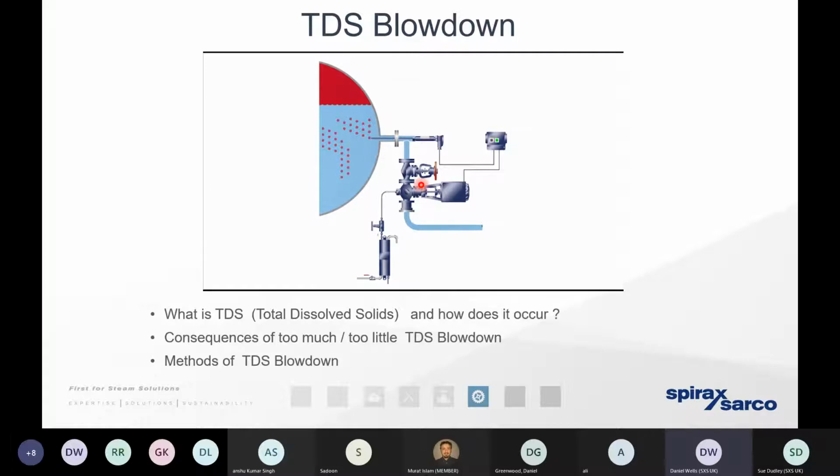The TDS needs to be at an appropriate level, and we measure it in parts per million. So typically the TDS could be managed by taking a sample from the side of the boiler on a daily basis, putting conductivity probes across that cooled sample. High conductivity, it's an indication of a high concentration. We open a valve at the side of the boiler. We bleed out a couple of gallons of hot water to waste. And then when the water level's fallen, it's replaced with a mass of colder water from the hot well.